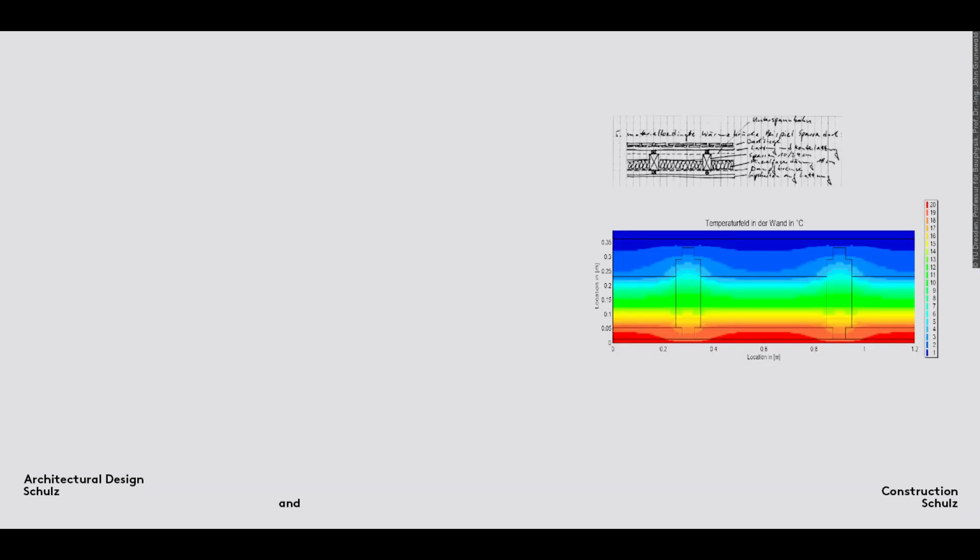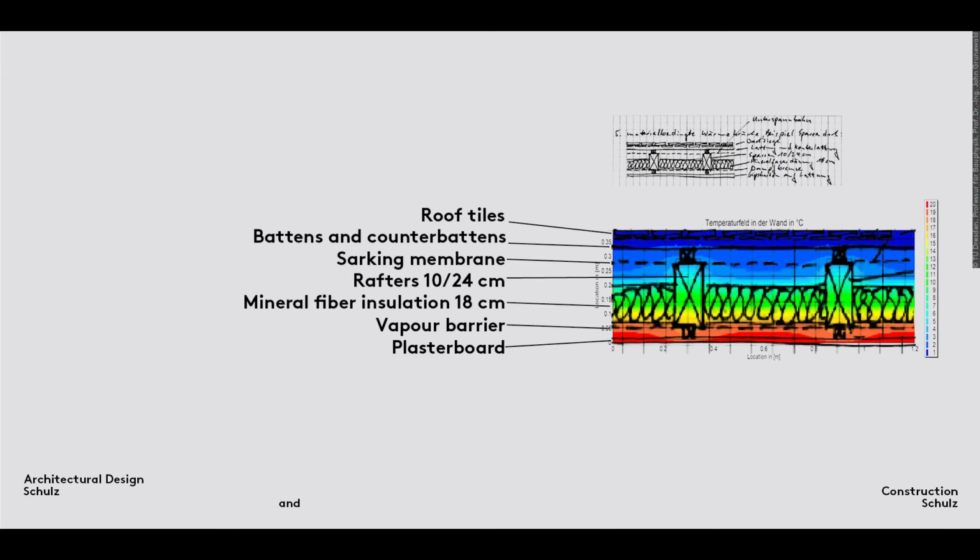Material thermal bridges occur predominantly where the fabric of a building consists of more than one material. Here, Professor Grunewald has produced an isotherm graph showing a rafter roof. From it, we can see that heat transmittance is greater at the timber rafters than in areas where insulation is present. This is because wood is a better conductor of heat.